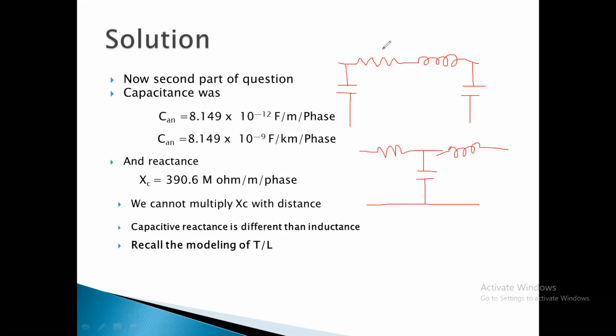You know that we use it for long transmission line, short transmission line. I'm not going into explanation over here. You know, there are three types of models we studied in transmission lines. Because if someone asks you, okay, draw a model of transmission line, you just write the total resistance over here, total inductance over here, and total capacitance here and here.